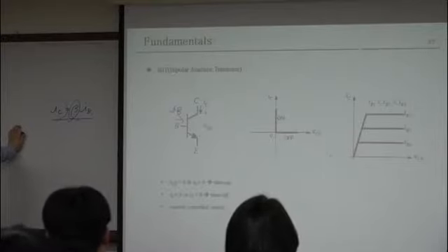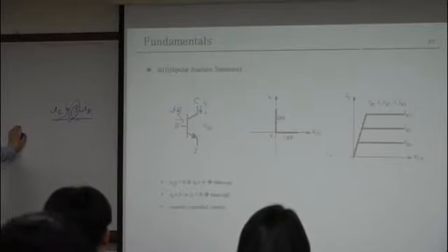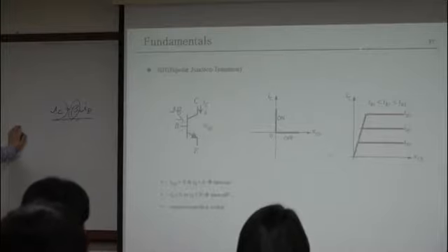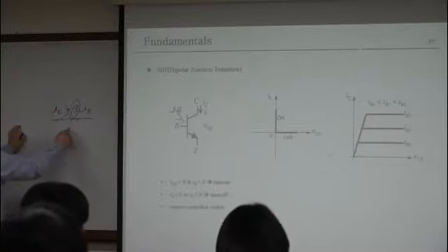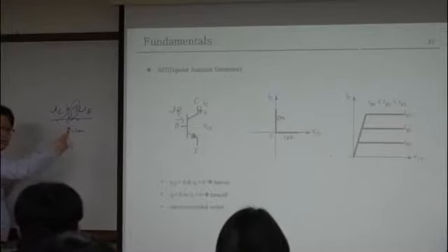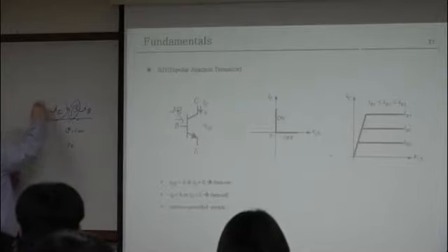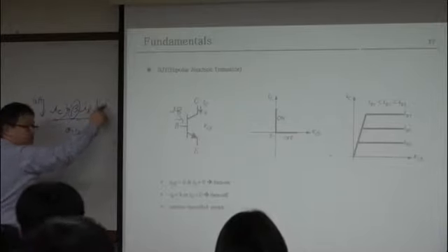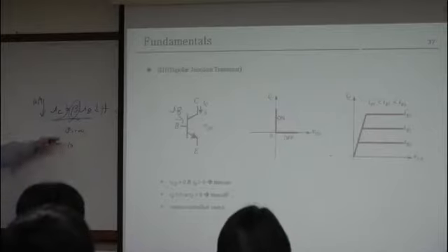In the electronics course, microelectronics course, beta was about 50, 100 or something like that. But in a power circuit, it's not that high. For example, it is like 10 or less than 10. It means if you control 10 amperes here, you should flow 1 ampere. For example, if your beta is 10.